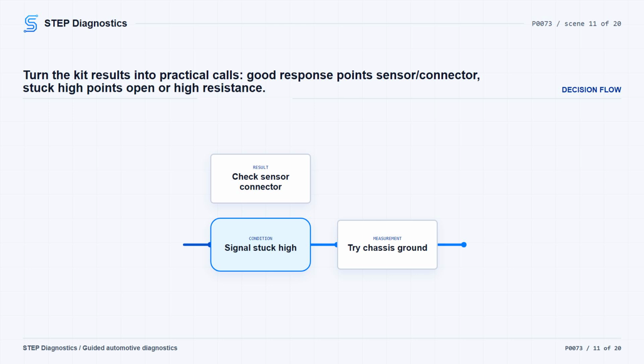If the open and closed tests work exactly as expected, the ECU and the temperature sensor circuits are testing good. At that point, the sensor is most likely faulty or has a poor connection at the sensor harness connector, so inspect that connector again before condemning the sensor. If a resistance table is available, measure the sensor resistance and compare it to the table. The actual resistance can vary +/-10% from the table values.